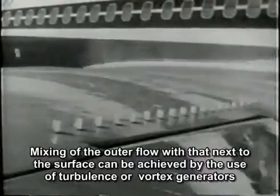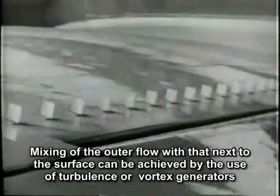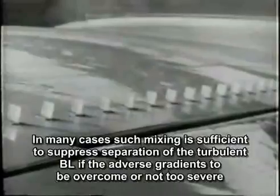Mixing of the outer flow with that next to the surface can be achieved through the use of turbulence or vortex generators. In many cases, such mixing is sufficient to suppress separation of the turbulent boundary layer if the adverse gradients to be overcome are not too severe.